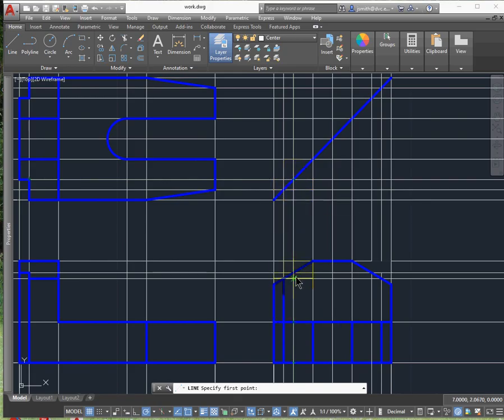And I'm using these construction lines. And there's one more, which is where the circle is. And I don't actually have that. So that's going to be the center line, but we want to do the hidden line. So I don't have the construction line, but what I can do is just go ahead and snap, hover over there, and that's going to be the hidden line for that circle, that half circle.